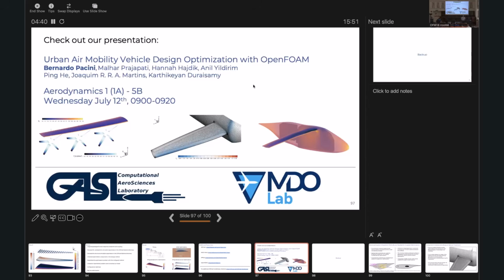We don't have adaptive refinement, so we're not necessarily manually maintaining the quality of the mesh. We do run the OpenFOAM mesh check at every iteration. So it's up to you to decide what you believe is adequate quality. For example, in the wing case, I relaxed that quality because for this tutorial, I just wanted to show how the wing deforms. I still won't let cells invert, for example. Negative volume would not work in the flow solver.